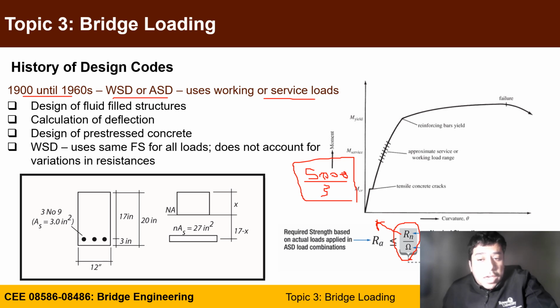This method is used when you have high uncertainty, similar to geotechnical engineering. Right now, they still use those methods. They do not allow much deformation at the design level, so you are not allowed to get much cracking in your concrete. They are also used in designing fluid-filled structures like water tanks. We are using it for calculation of deflection, cracks, and stresses in prestressed concrete.